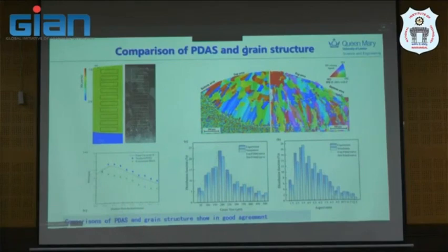So you are looking at the dendritic growth on the top left-hand side here, and then looking at the segregation profile of niobium, right? This niobium is the important segregation profile for the Laves phase, right? And you're looking at different locations in the melt pool, I believe. This is only one deposition, one layer. Only just one layer. So okay, this is only one layer.